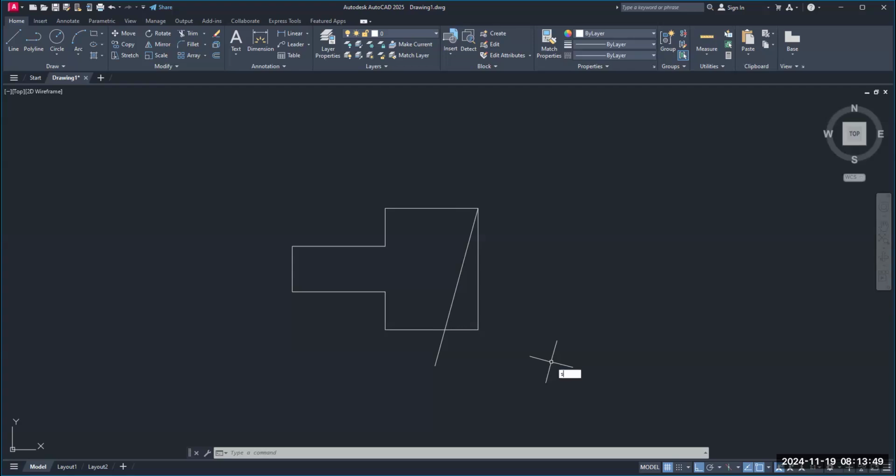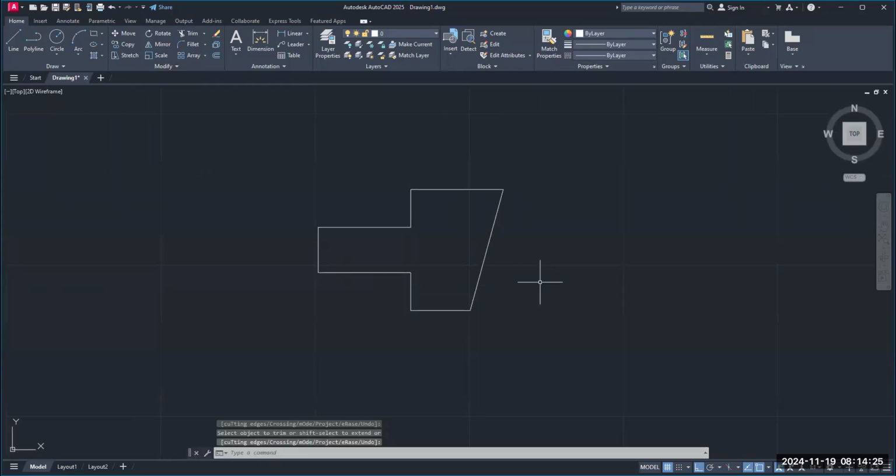Now, I don't need the snap angle set at 75 degrees anymore. Okay. So type in snap angle again. You got to spell it right though. Okay. Enter and type in 0, enter. It's a nice tool. Now, we know how to use trim. There's a pair of scissors up here on the menu bar. If you're more comfortable with that, you can click on trim and come down here and let's trim what we no longer need. And then hit enter. All right. Is there any questions? You're doing good. I'm very proud of you.